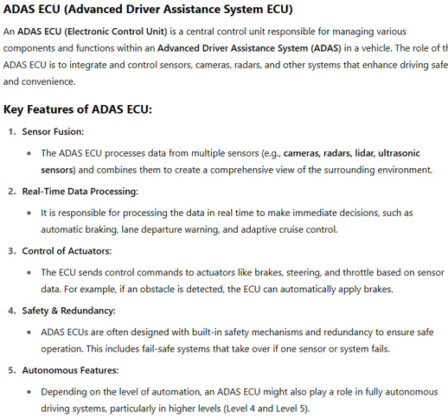For detecting an obstacle, we use the camera to detect some obstacle, and we confirm the distance from the camera to that object using lidar or ultrasonic, or even the radar sensor. So we can stop using a brake or steer the steering wheel. Also we can step on the throttle for acceleration and deceleration.